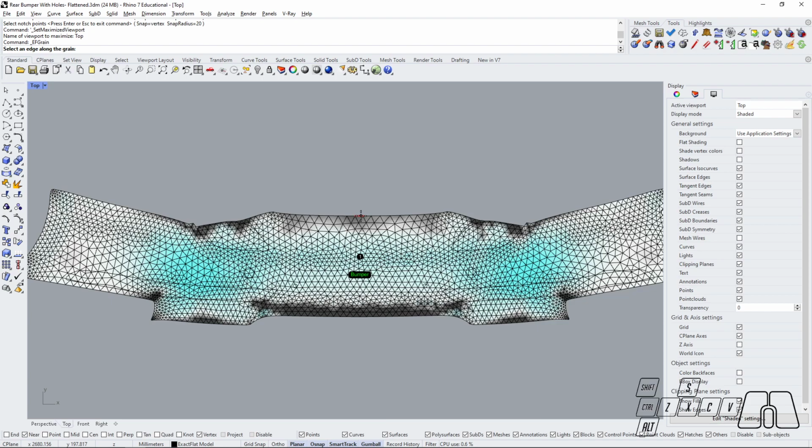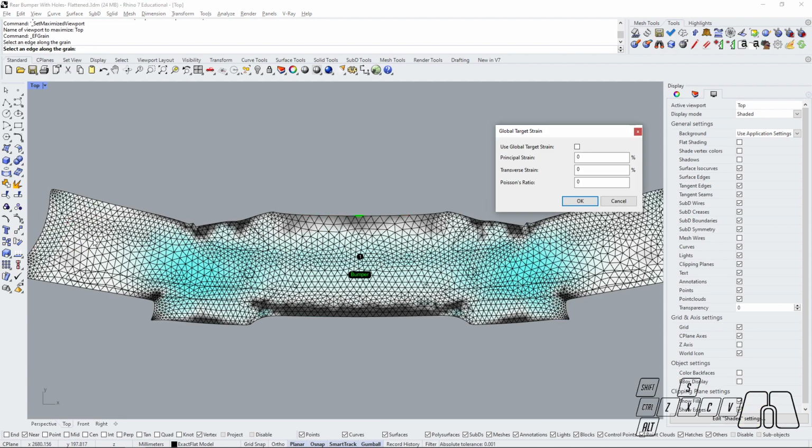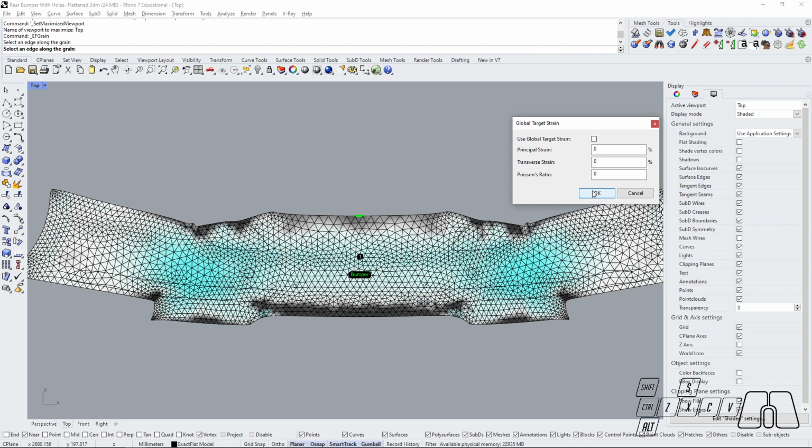In this case, as we're using a paint protection film, there's not going to be weaves in the material or fiber, but this tool can mark as well the stretching direction for my material. So if I'm wrapping the material from left to right, I could mark a horizontal grain line to mark that this pattern will be wrapped in that direction. And while doing this, I could just hit OK, and that will basically transfer this grain line as a simple line in the final DXF.